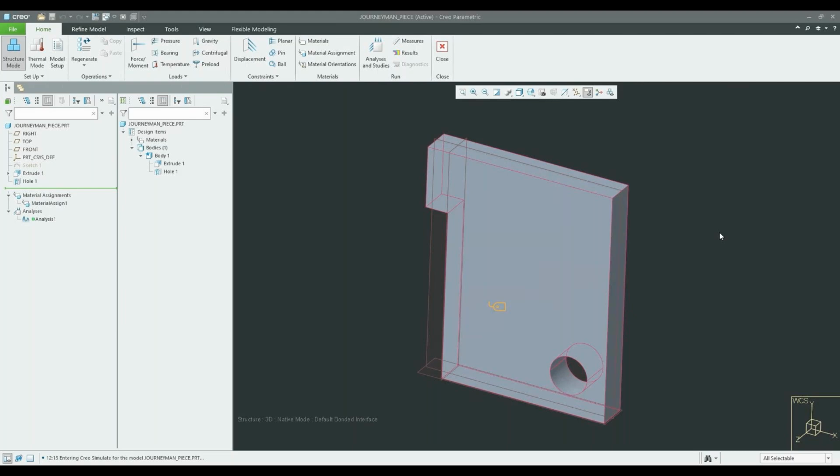Well, maybe this number here is supposed to be 0.27, and you do like I do on occasion. You have a fat finger and you type in 0.72. Trust me, a Poisson's ratio off by that much will make a large difference. But I can't validate that Poisson's ratio if I don't know where the value comes from. So that's how we can create our own materials.